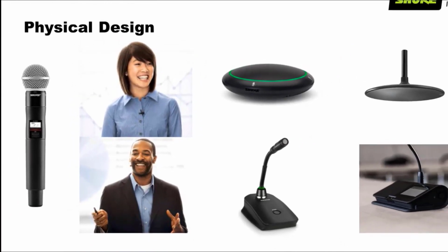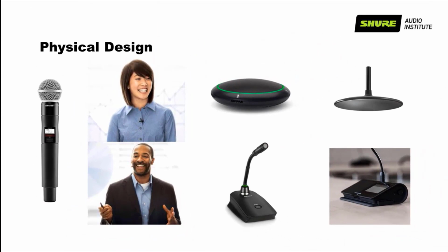Out of those three options for miking an individual, the handheld is probably the most universally known microphone when people see a microphone, but it also requires you to have some idea of what you're doing, which is holding the microphone pointed at your mouth, not down by your belly button, but actually up where it can make a difference. And then you move to the body-worn mics, which of course give that more consistent sound, with the head-worn mic kind of being the preferred option there.